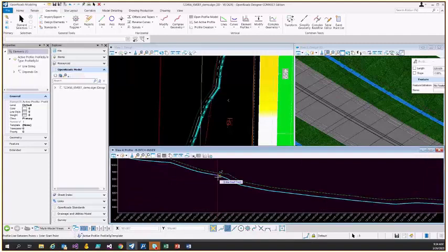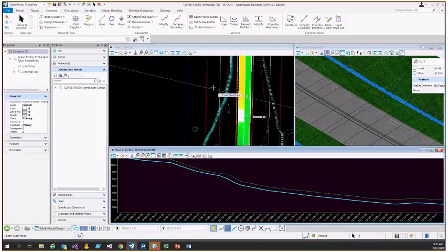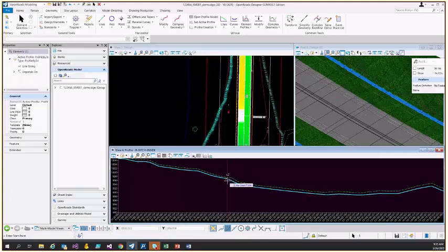You can easily come to your geometry tools under the vertical section and draw in a ditch profile. The key is to not ever go above, because clearly it won't solve then, because this is showing you that minimum required. The further below you go, which is okay to do, keep in mind that to retain this fore slope, it's going to keep pushing it out more. So if your grading changes as you get out more, you could see some differences happening. But for the most part, that's probably good enough.